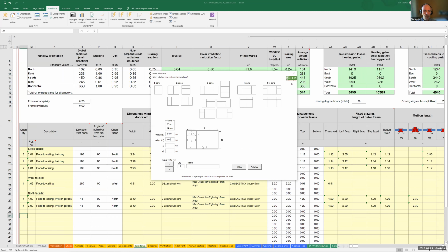So what it does here, for example, is it works out the length of mullion, which is between, now I should say this, for those people who aren't familiar, this means this is an opening window, this little triangle here. And these two are therefore fixed. So this mullion here, this part of it is fixed. This mullion here will be defined as a different width because it goes between an opening window and a fixed window. And this transom here also goes between an opening window and a fixed window.